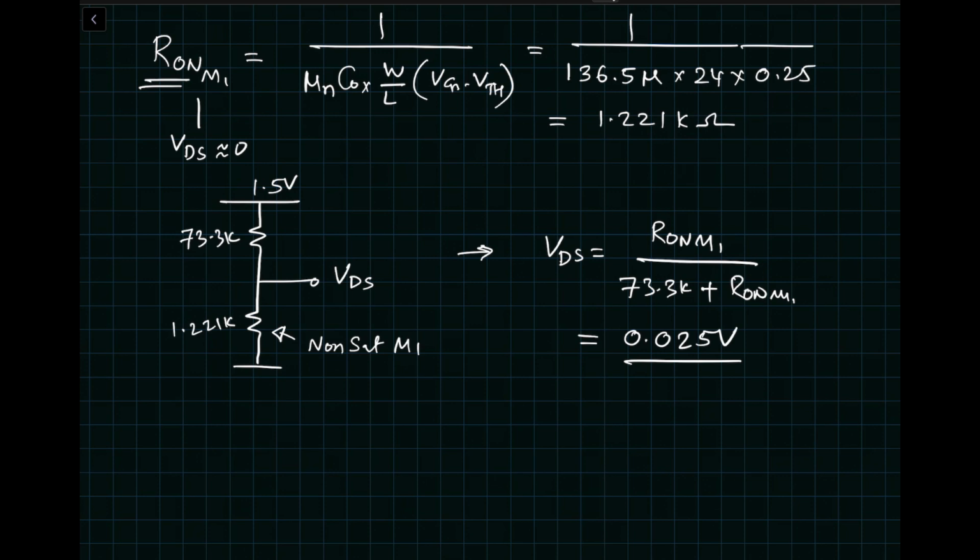So we just went through an exercise where we put NMOS transistor through cutoff, saturation and non-saturation by playing with a couple of resistors, just like what we did in case of bipolar case. So this should give you a good feel for different modes of operation of both the devices. Now we are going to compare both bipolar and CMOS head to head for their maximum usable gain that you can achieve out of them. Now this is something that gives you a perspective in terms of capability of both the devices, and it's an excellent interview question.